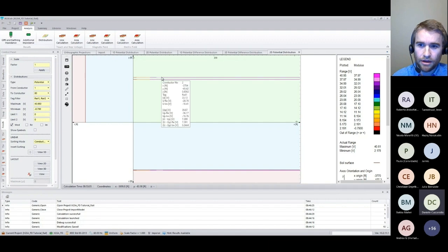And in the adjacent rail, we have a similar one, but there's a little bit of a phase difference between one rail and the other. So that's going to relate to the vector difference between one rail and the other. That's going to correlate to rail-to-rail voltages that can cause some misoperation in that rail-to-rail signaling, or the track signaling.